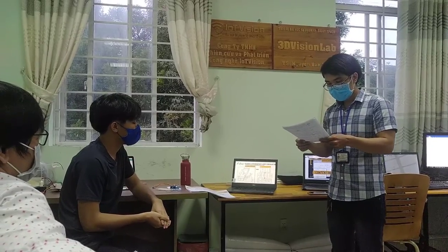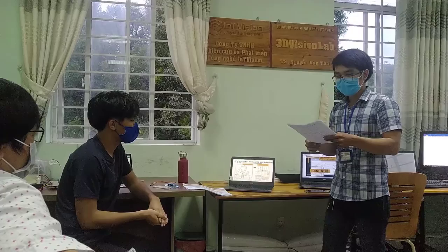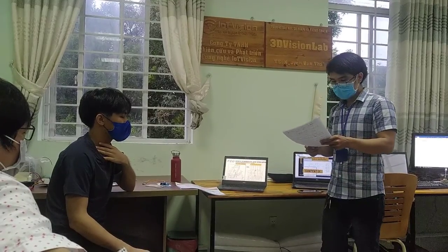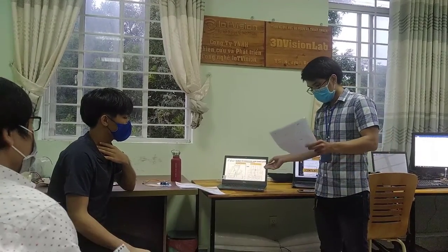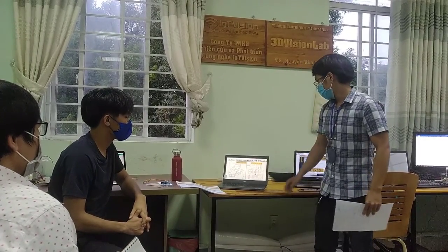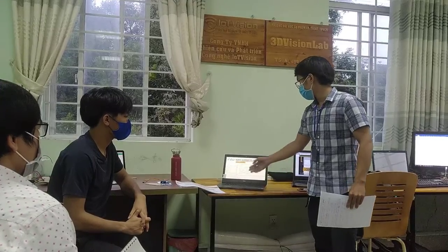In the table, there are the joint angle, the link offset distance, the link length, and the twist angle. The parameters in the table are substituted into the transformation matrix, and I calculate the endpoint coordinate of the single leg. We obtain x, y, and z, and from it, the result.